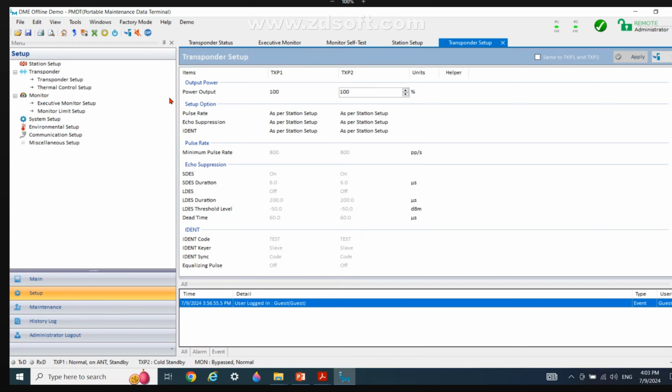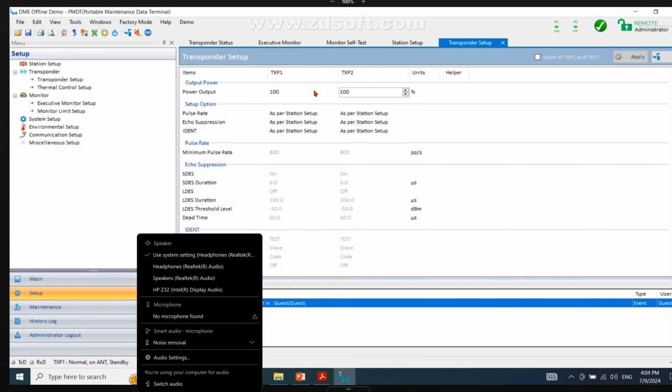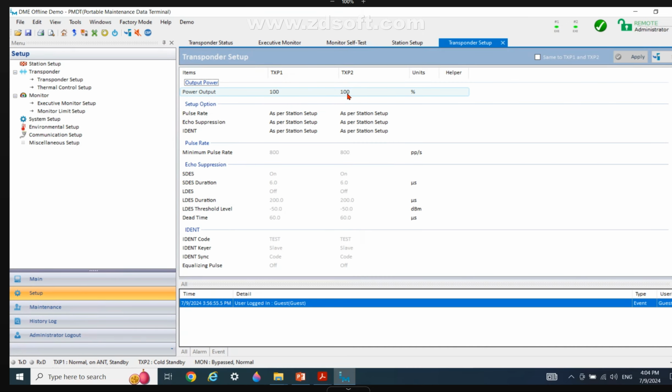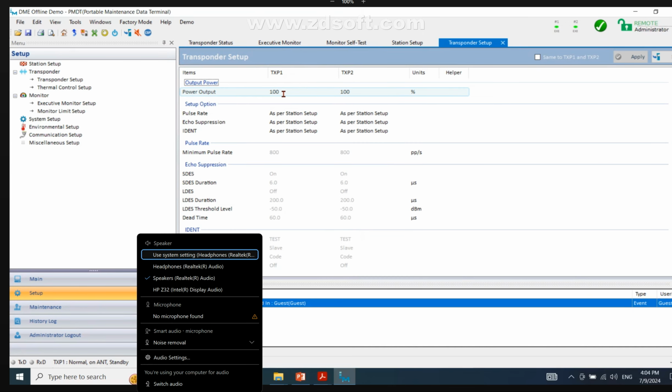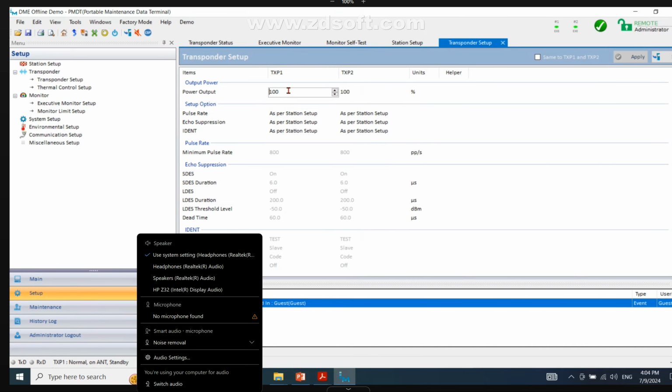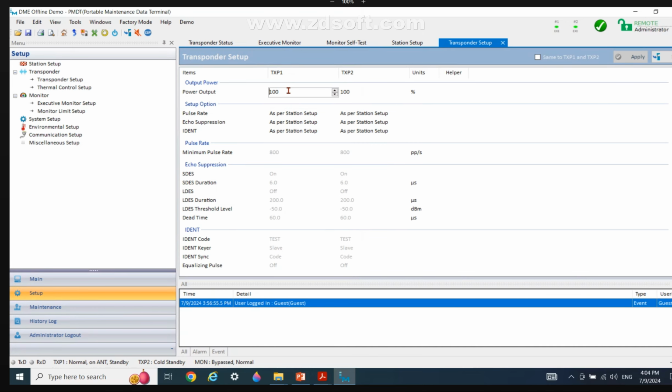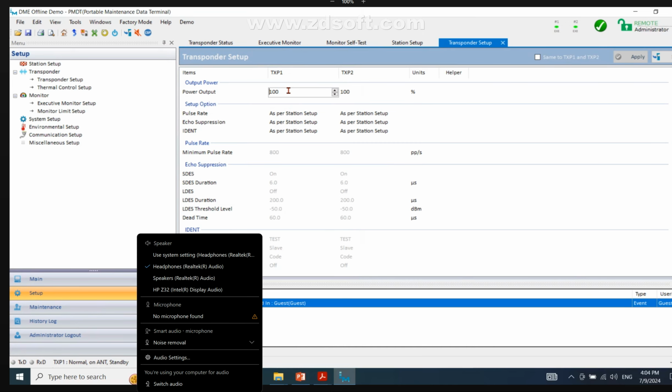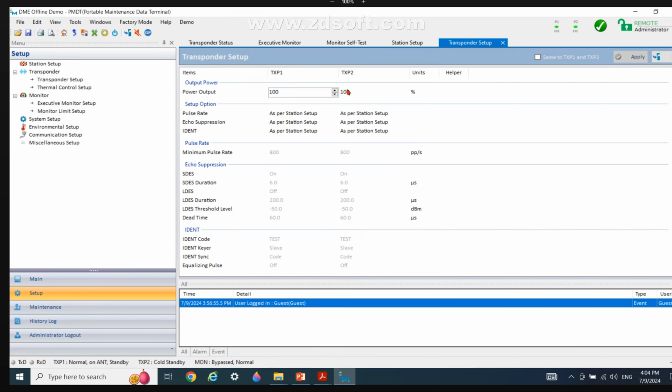This is percent power. So what we can do using this, it is not advisable, but I have also seen this. If I want one transmitter to be at higher power and the other transmitter at lower power, or say our FIU aircraft is reporting differently, saying for transmitter 1 power is sufficient, but for transmitter 2 please increase power a little more, we can do this, or reduce power, from here.